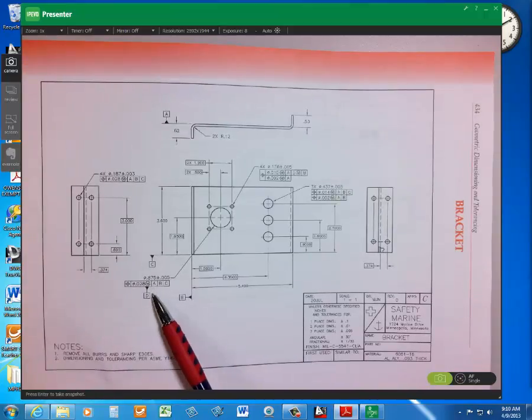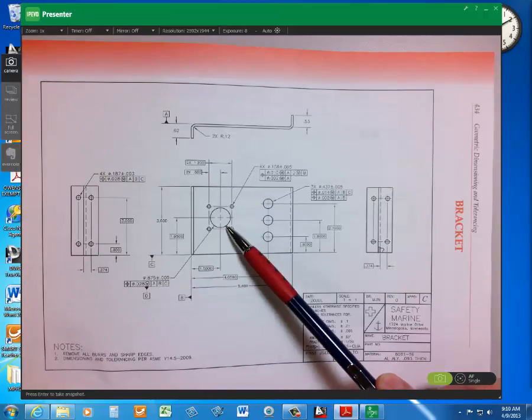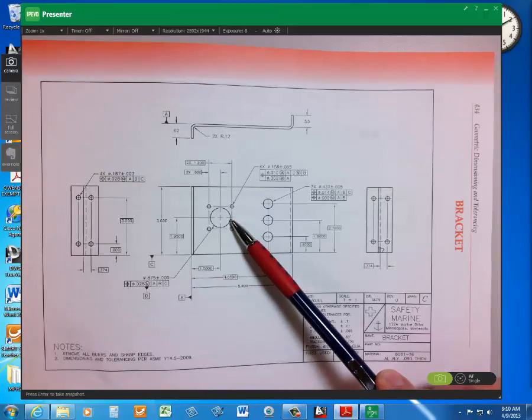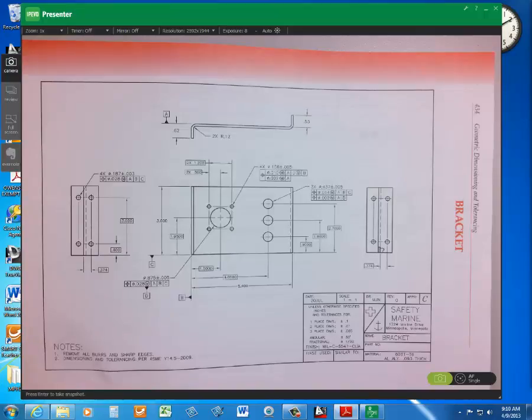So at maximum material boundary of where that boundary of the axis would end up, at maximum material condition, which is when the hole is at its, the position tolerance is at its smallest, right? We depart from MMC toward LMC.